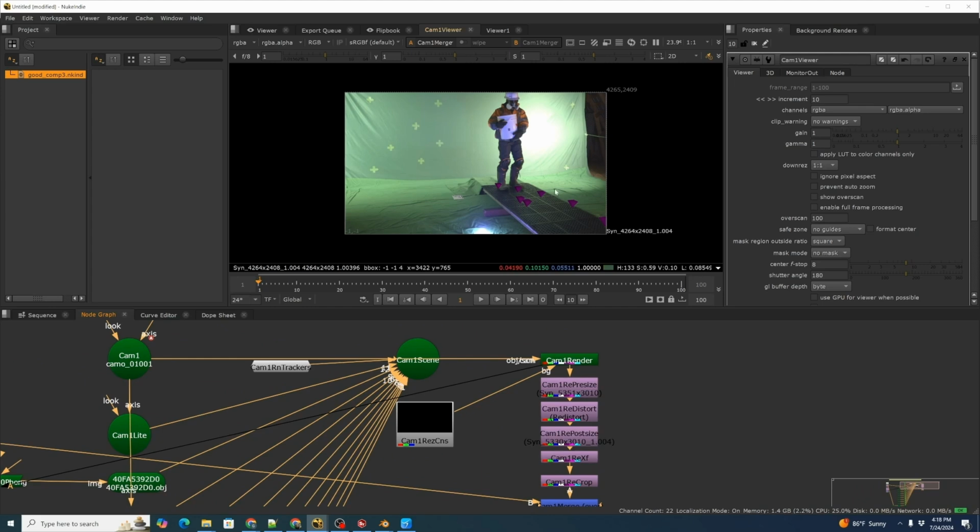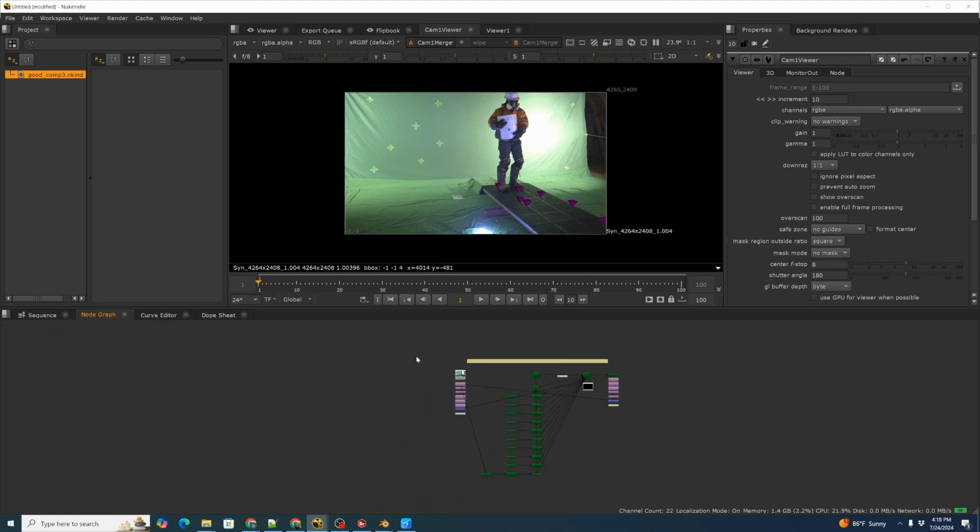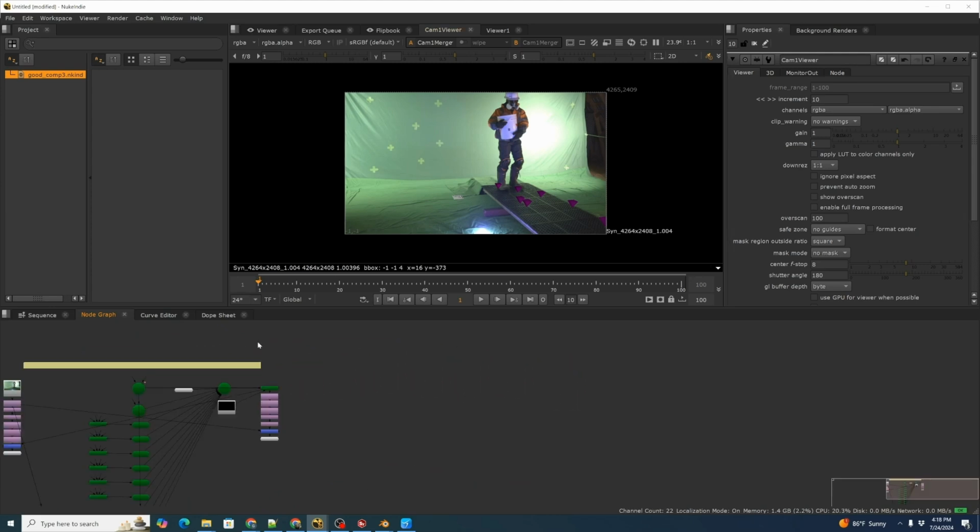When we bring in the background video, we're going to verify that those all line up. So let's go ahead and grab a hold of all these and let's move it over here. And we have a problem here is that right now the default frame starts here from 1 and see nothing's happening. And that's because our actual frames go from 1001 upward to about 1171 in this case. That'll get fixed when we do our Autoshot export.